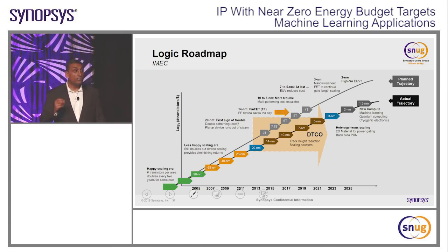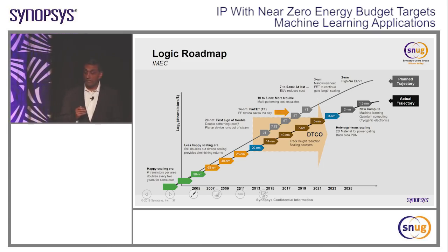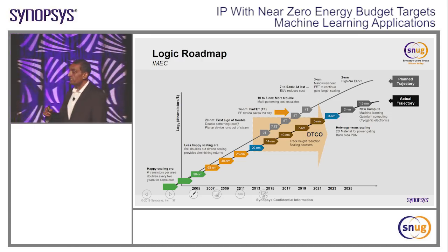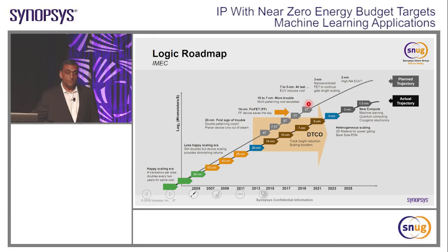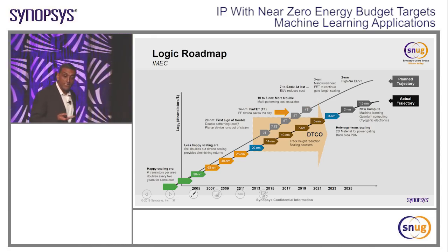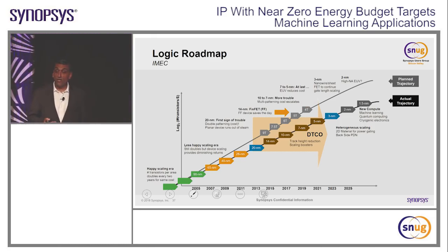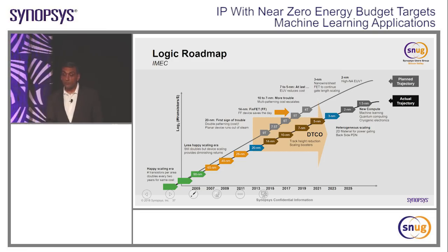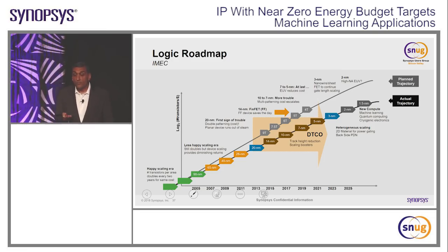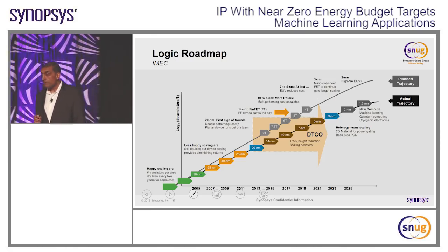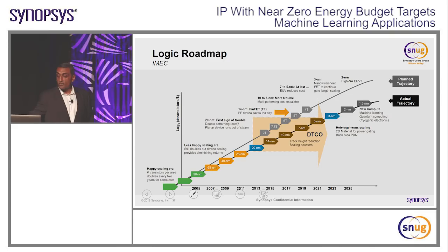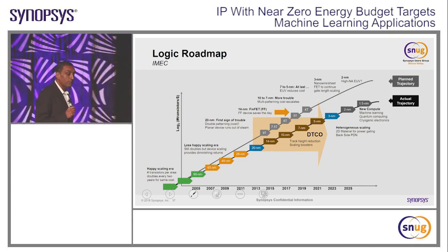So firstly, the logic libraries, the Ts. So you move from 9-track libraries to 6, 4 maybe. So the low track height in a library helps you to reduce power consumption. If you increase the threshold voltage of that library and add long channel variants, you further reduce your power consumption. That's one point. The second point is this concept called DTCO, Design Technology Co-Optimization.